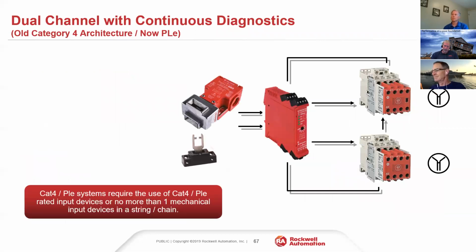So in effect, the circuit looks very similar to category 3, with the big caveat that we discussed a little earlier: if we had a nested fault, if we had an issue that we could trick the system into believing wasn't there, in the case of the 2 switches in series where one was welded or otherwise broken, we could actuate that second switch to have the relay not notice that we have a broken switch. So that's not acceptable in category 4. If you're using electromechanical type devices for a category 4 implementation, it is one device per channel, so that you don't have any nested fault capability.